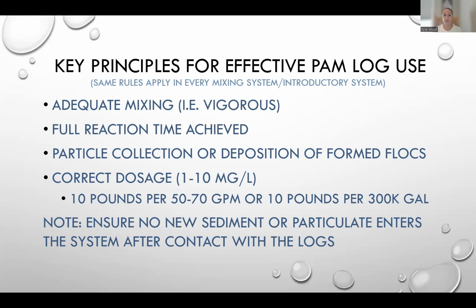If we test the material, we know we have the right formulation, and something is not working on an application, 99% of the time one of these fundamentals has not been met. So these are really important things to make sure we're familiar with. We have to have adequate mixing. Vigorous turbulent mixing in the channel is best. The more mixing, the better to form those big flocks so they can settle out.